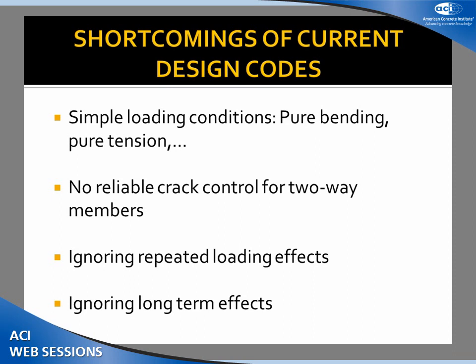There are some shortcomings in the current design codes. They are just considering simple loading conditions like pure bending or pure tension. They don't have any reliable crack control for two-way members, and they ignore repeated loading effects or long-term effects.